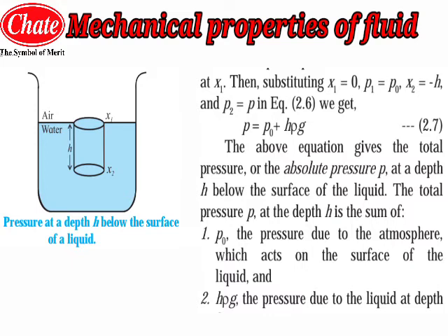This is nothing but the summation, which gives us the absolute pressure P, which will be P0 plus rho hg. This is the derivation we have obtained after considering the top surface of that imaginary cylinder to be equal to the water level or the water surface.